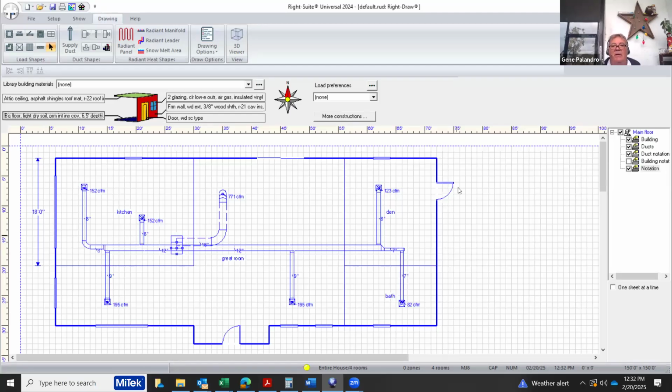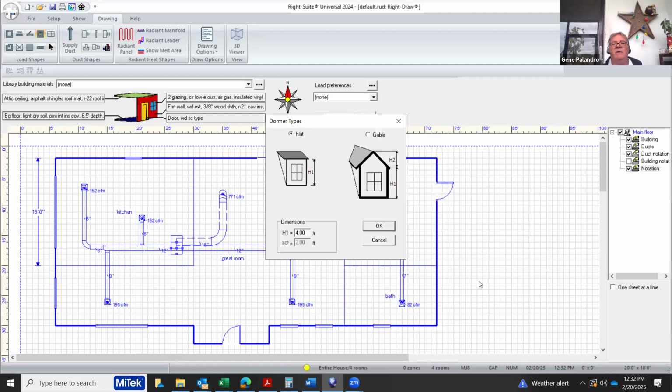And particularly on this west wall, I'm going to go ahead and drop in a, what do we need here? We're going to drop a room over here to represent the garage. Okay, so it's just a matter of going over and telling it, I've got a 21 by 18 garage here.